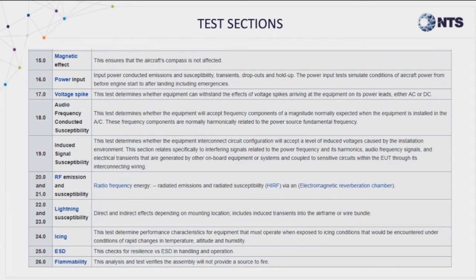And the second part of the question said, who can sign off that the test goals were met? If NTS does that testing, or any test supply house, we would sign off via test reports, engineering analysis with data to show that the test was performed, how it was performed, the exact results that were obtained, were they within the margin of the requirements, and if they were, certified that the product met the spec. Correct. And that's based off of the test procedure that is pre-agreed upon between the entity looking to certify and the FAA or whoever the certifying body is.